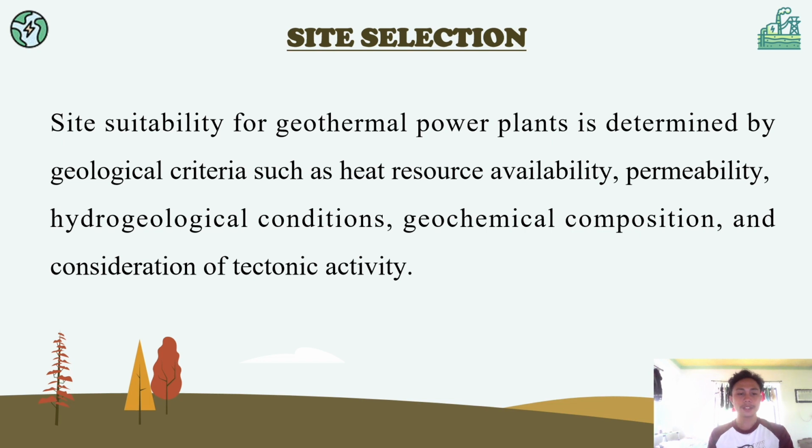Site suitability for geothermal power plants is determined by geological criteria such as heat source availability, permeability, hydrogeological conditions, geochemical composition, and consideration of tectonic activity.